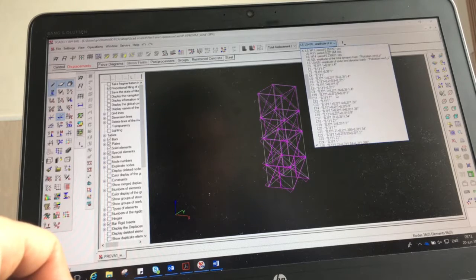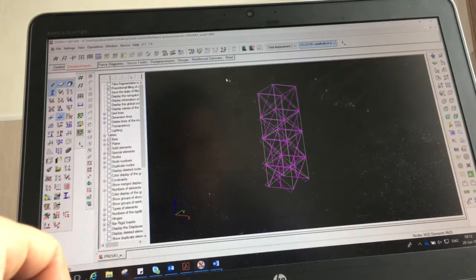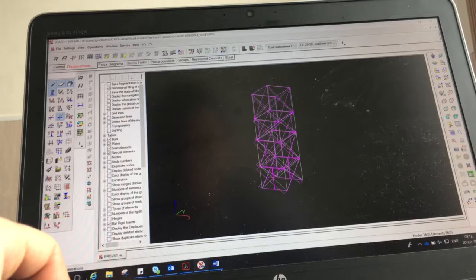Anyway, Scad is doing this analysis. Also available: accelerations, inertia forces not calculated, weight of modal masses. Information is not available for the chosen system of displacement. If we change the displacement and choose one direction, weight of modal masses will be available.